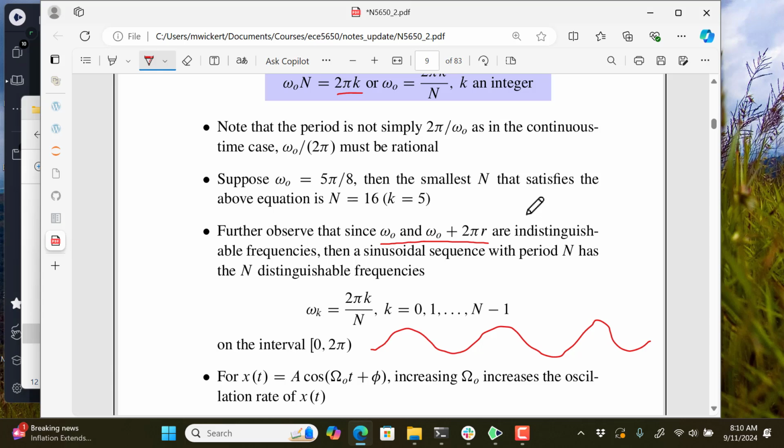And I guess a good way of thinking about that would be, again, if I was thinking of this lookup table, I could stride across the data. If you have an array of data, and each time you come through the loop to take that data out and send it to the D-to-A converter, you could take one, then the next one, and so on. If you decided to just stride by 2, you would take the first one, then the third one, then the 5th one.